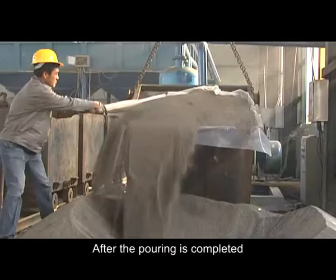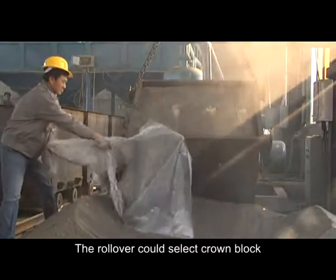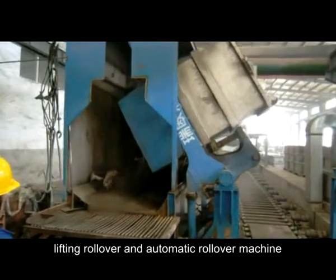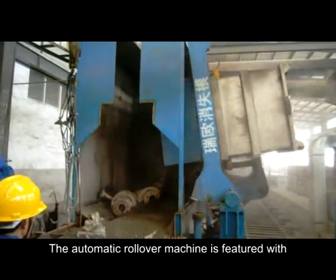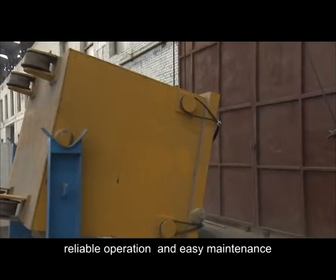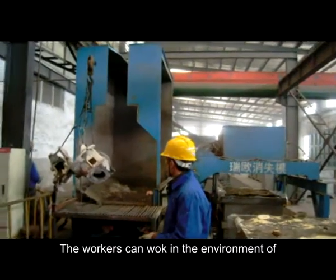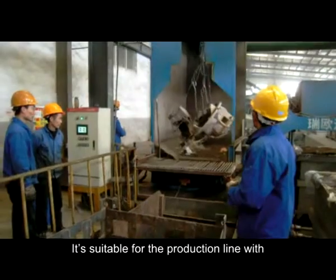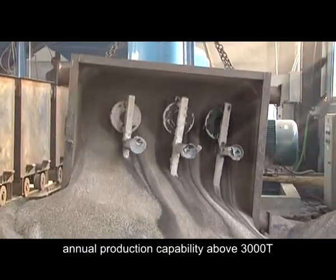After the pouring is completed, a rollover of the molding flask begins. The rollover could select crown block lifting rollover or automatic rollover machine. The automatic rollover machine is featured with high efficiency, less dust, reliable operation, and easy maintenance. The workers don't have to work in an environment of high temperature and dust. It is suitable for production lines with annual production capability above 3,000 tons.